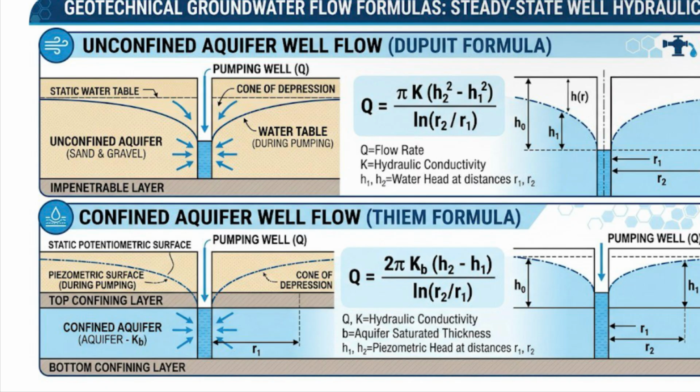The assumption of purely horizontal flow becomes increasingly inaccurate near the wellbore, where vertical flow components are significant due to the steepening of the hydraulic gradient. Additionally, it ignores the seepage face that typically develops at the well wall in unconfined aquifers. Despite these theoretical gaps, the formula remains highly effective for calculating discharge at significant distances from the pumping source.